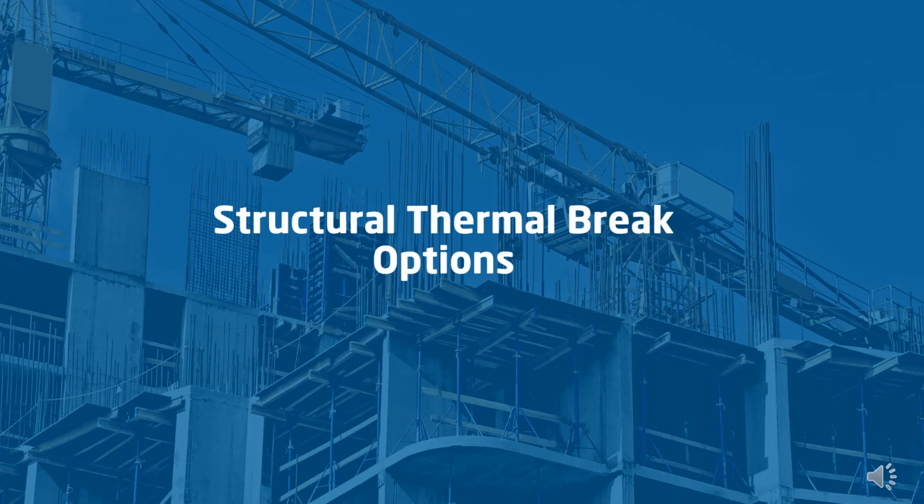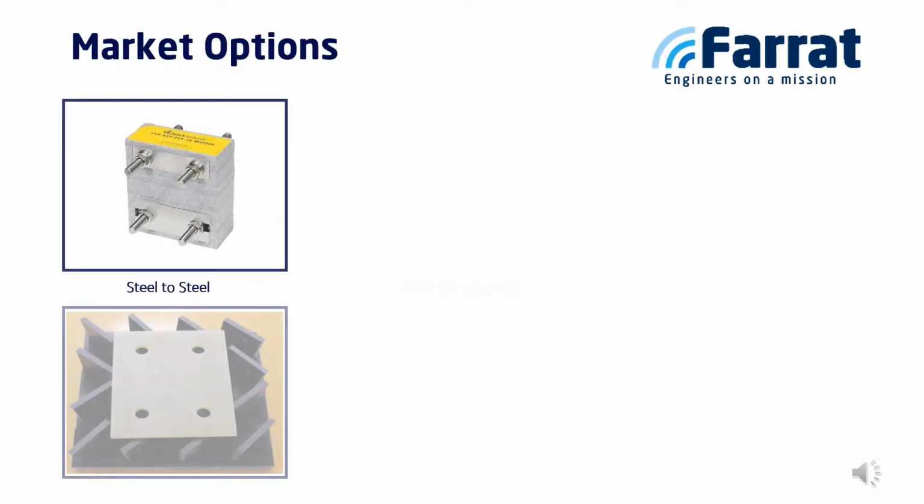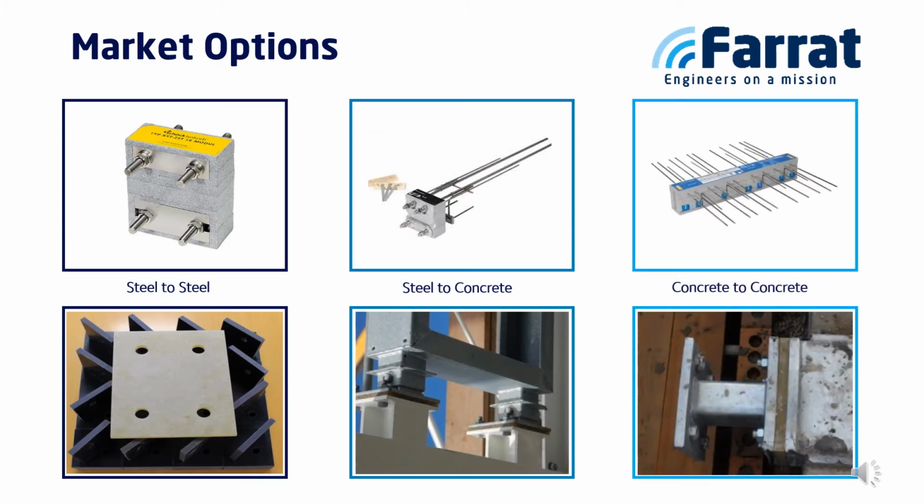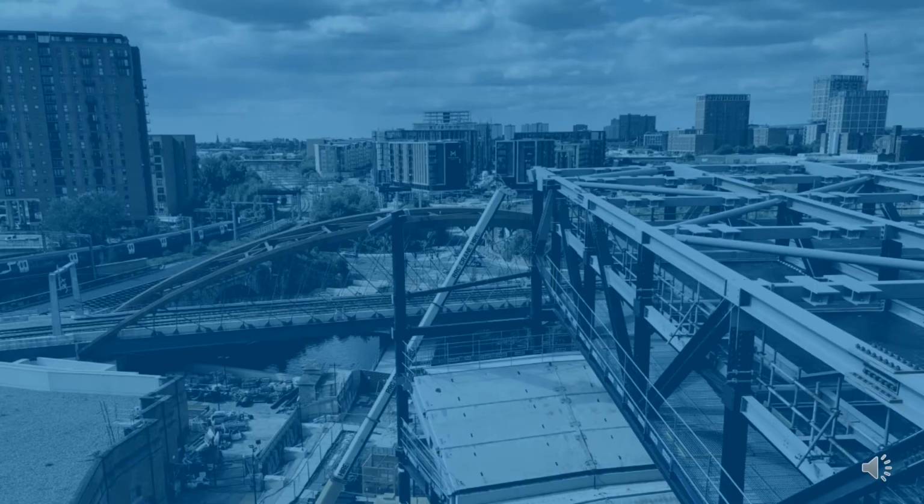Well, there are two principal types of structural thermal breaks, mechanical and solid-state plates. Mechanical thermal breaks include combinations of structural components and compressive insulating materials, which are used to compensate for the poor thermal performance of the continuous steel elements. The alternate type, solid-state thermal break plates, are used in conventional connections as structural spacers that also have a high thermal performance. In respect of energy loss, all materials have a thermal conductivity value.